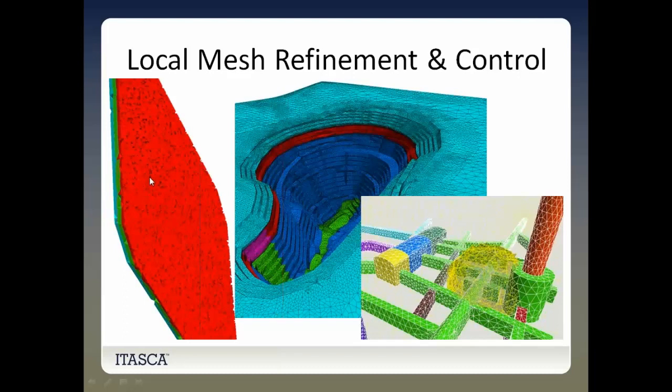Here is another interesting example on the left. It's an example prepared for a rock flow analysis for 3DEC. These are independent little blocks that you can see maybe more or less clearly on your screen. But we needed to produce tetrahedral blocks for this 3DEC model that have all exactly the same size. There's a procedure available, and there's a paper that was made at some point that shows exactly how to use KUBRIX and Rhino to produce exactly a prescribed distribution of blocks according to a spatially defined field.